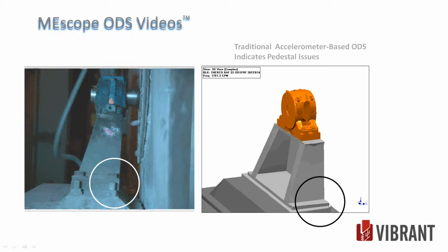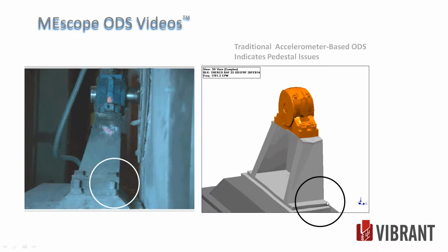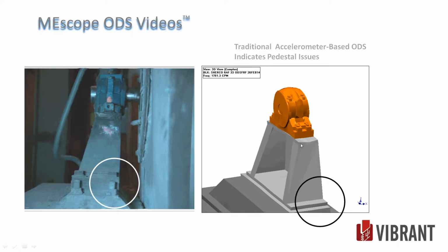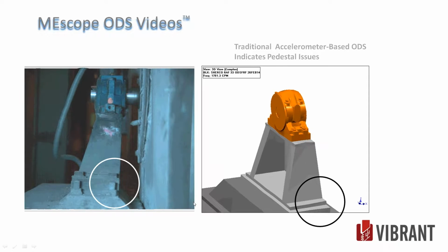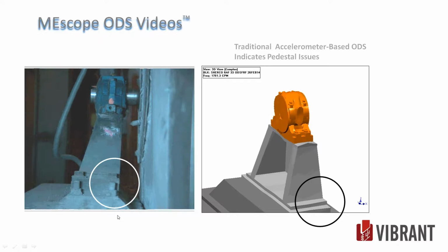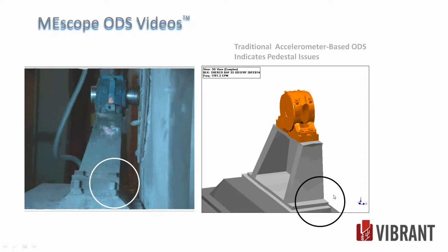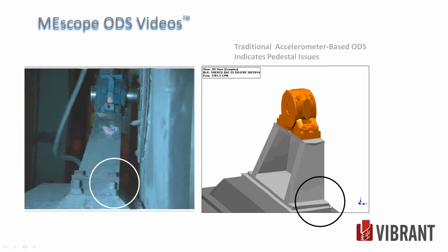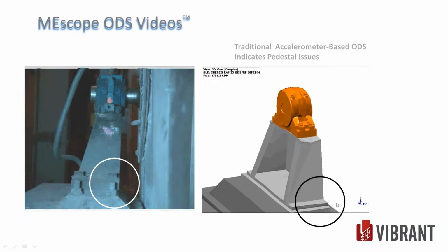When you look down here, we did take measurements across each interface all the way up on every corner, and we mapped it pretty good so that we could see if any of these bolted interfaces were loose. And we see a little slight instance of out of phase motion.